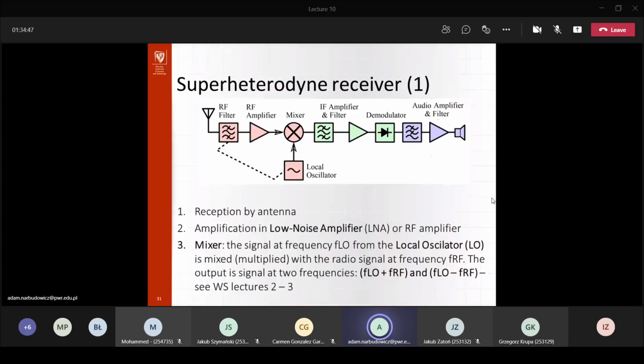The rule is simple: if you have any multi-tone excitation applied to a nonlinear component, you will also get the intermodulation components. In theory, this is exactly why we have filters at every stage. In a perfect world, you shouldn't have that problem, because the filters should filter out all of the undesired frequencies, assuming they're well tuned, the filtration is very good, they are high order, and so on.